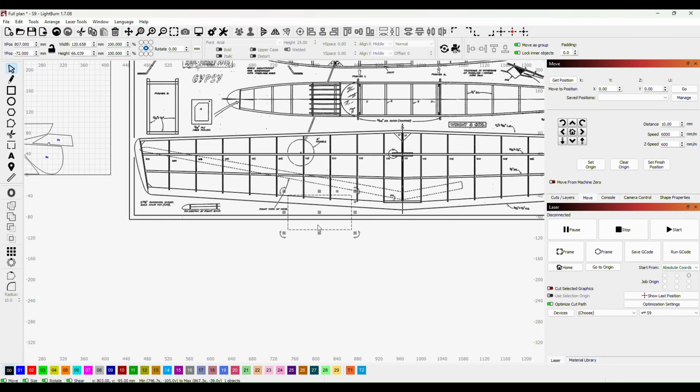So I'll bring it down here to start with, because there's something that we have to do with it. I'll rotate it round, and then I'll make sure that we're exactly level by going to nodes, hovering over that edge, pressing A, and now we're level.